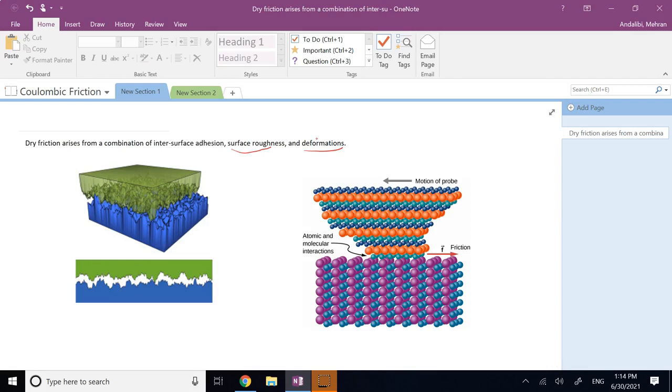But one of the other reasons, which we probably do not discuss a lot in elementary dynamics, is surface adhesion. The matter of fact is, when two objects are in contact, the longer you leave them in contact, or the smaller the sliding velocities, the better chance they have of forming intermolecular bonds, and that leads to adhesion.